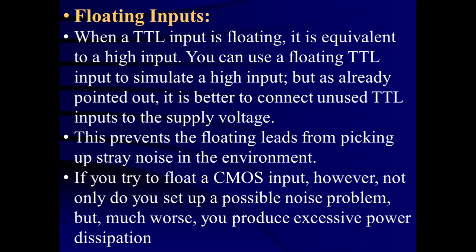But it is advisable that the unused input should be connected to the supply voltage. Either it should be connected to VCC, the positive terminal of the supply voltage, or it should be grounded, depending upon the situation, so that the output will not be stuck.